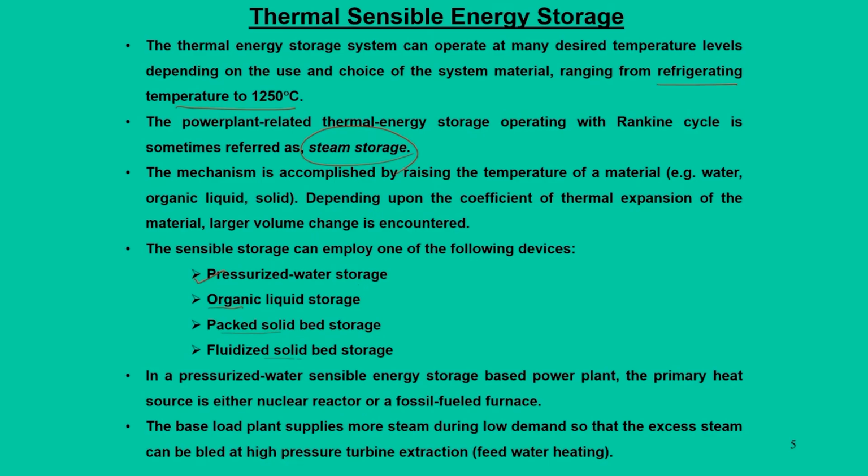Another advantage of this system is that it can be integrated with any kind of power plant or base plant, which can be operated through a nuclear reactor or any fossil fuel furnace. Here the entire idea is that the base load plant supplies steam during low demand, so that excess steam can be bled at high pressure turbine extraction. This is something we call feed water heating systems, or the regenerative mode of operating a steam turbine in a conventional power plant. Whatever steam you tap at low pressure can be stored.